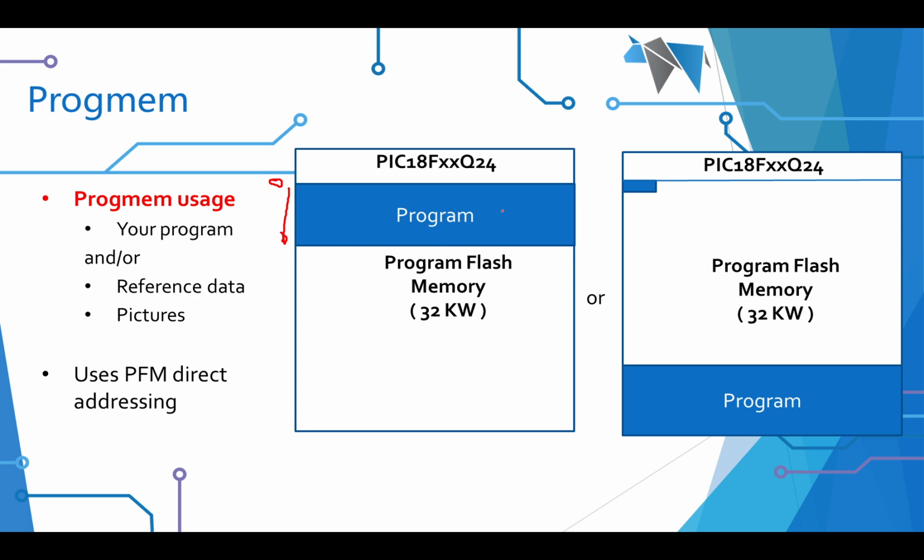Other compilers might give you a little jump statement at 0, and it says jump to this location here. And this diagram is sort of important because depending on what type of compiler you're using, whether it's a bottom loader or top loader, if you write something here into program memory, it would work. But when you're using a top loading compiler, it would obviously destroy your program. So just be careful and be conscious of the type of compiler. We're a bottom loader. GCBASIC is a bottom loader. It always starts at 0 and works its way up.